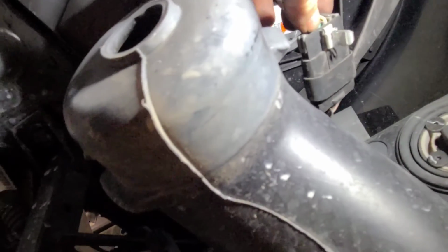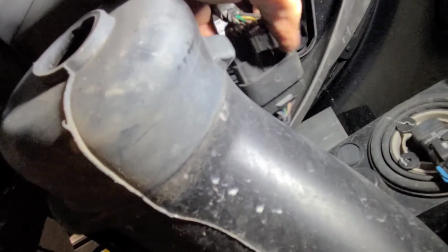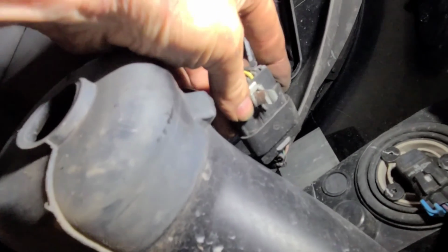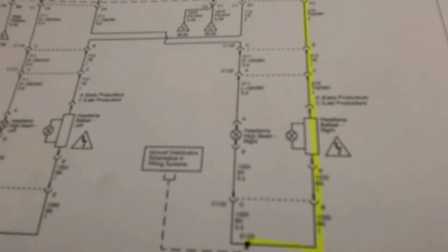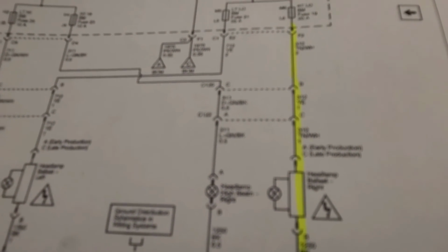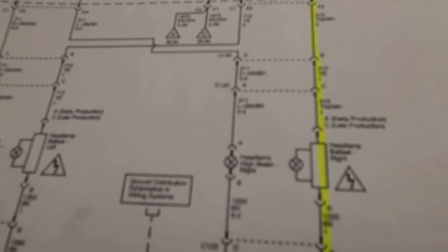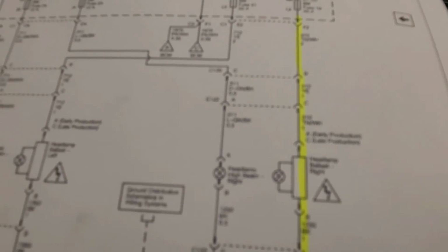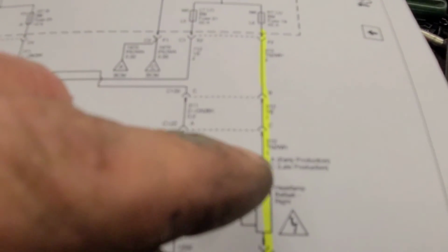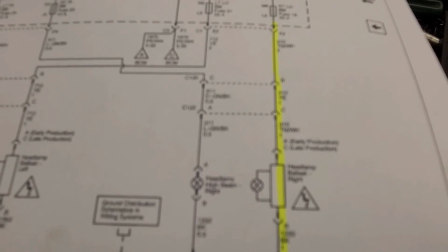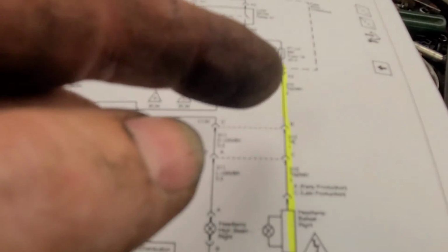Why has it changed color? It's tan white on that side, but it's yellow on that side. Is that the way it is on the connector? Oh, it is. Look at that. So we must be on... That's hard to say. Well, we're going to check that tan white wire, or the yellow wire, because it changes color for some stupid reason. It's tan white, then it becomes yellow, then it becomes tan white. So we're either in pin B or pin C.